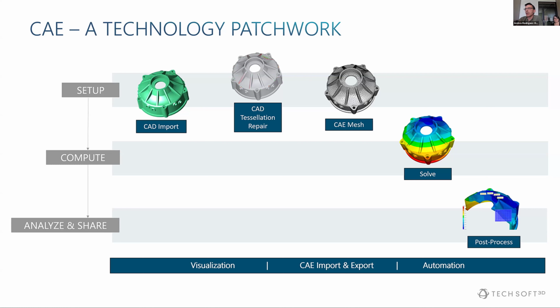One good way of looking at all these technologies is to look at what I call the standard workflow. This is a workflow that you will find in a solver-centric application. It goes very easily from the setup of a simulation to its resolution, its computation, and then the post-processing side. In the setup stage, it's all about providing all the data necessary for the solver. A big chunk of this data is the geometry, and that's where you have a few technologies lined up, importing CAD files. Of course, some applications still use STL, but it's highly preferable to access the CAD definition, so being able to read different native formats is interesting.